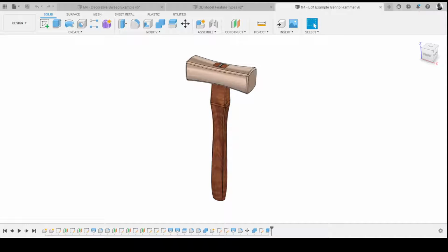And if you can't get them to fit one of revolve, extrude, and sweep, then lofting is where we're going to go. So we can see that we've got a hammerhead here, which gets smaller in the middle and wider again, it flares out. You couldn't do that with an extrude easily, because you could taper half of it and then mirror it across, but then you'd have an angle. You wouldn't get that nice, smooth, curving shape.